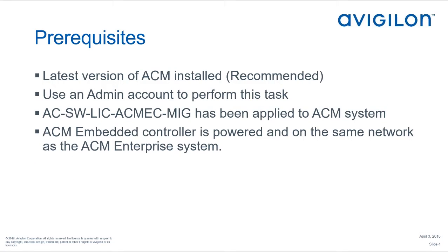It is always recommended you have the latest version of ACM installed. For current software and upgrades, please visit the support page at avigilon.com. Make sure that you are using an admin account with the ability to add or modify panels. Verify that the ACM EC migration license has been applied to the ACM system.